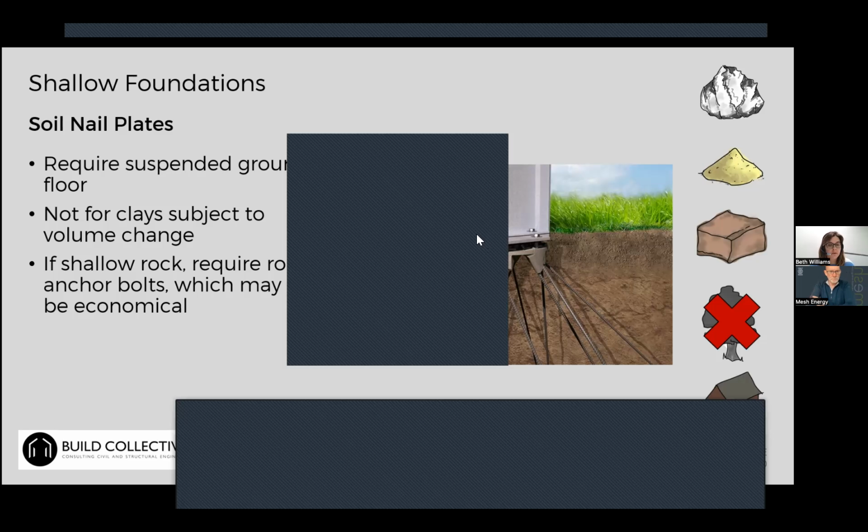The main one that has more of an impact on carbon than changing the aggregates is reducing the cement content, and there are a couple of ways you can do that. The most simple way is to reduce the concrete grade that you need. If you can minimize the number of point loads, for example, you can go back to an unreinforced strip foundation that can be a lower grade concrete with lower cement in it in the first place. Then you've also got the cement replacement options: pulverized fuel ash, which is PFA, and granulated ground blast furnace slag, which is GGBS.